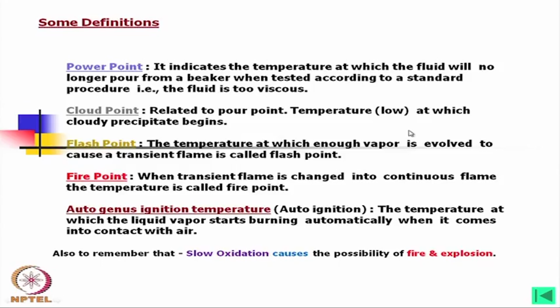In fact, if you look into the catalog for an oil, it is mentioned with different graphs and information. So, you can select a proper oil by looking into that. However, if you become an application engineer, you will find that those who manufacture fluid power components also provide suggestions on what type of oil can be used for what type of operations.